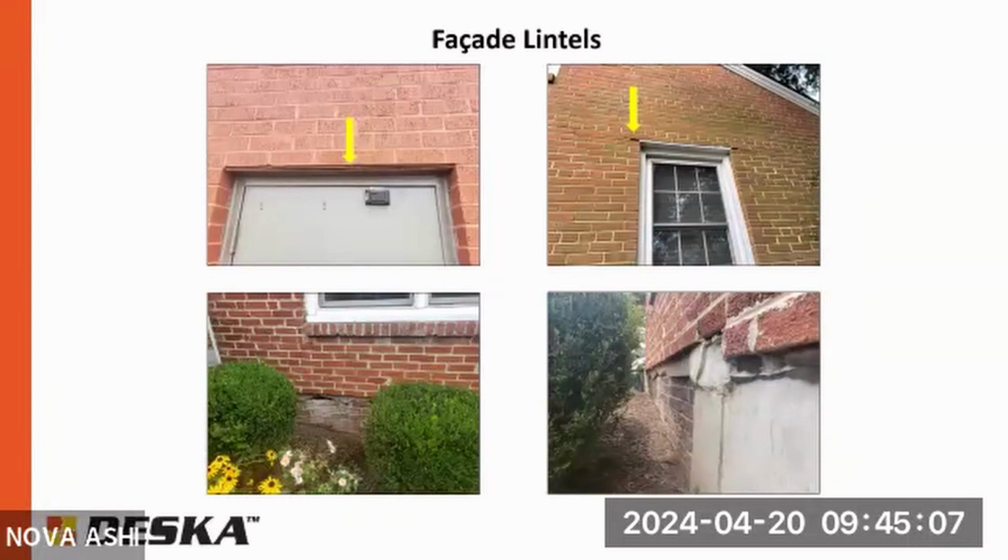Usually it's not really considered a structural issue if it's just supporting a brick facade. But a brick facade is very heavy. Although it's not supporting the structure, it is still very heavy and it is being supported. If it was, let's say, a full masonry wall, then it would definitely be considered a structural issue. But it only gets worse over time, like many things.